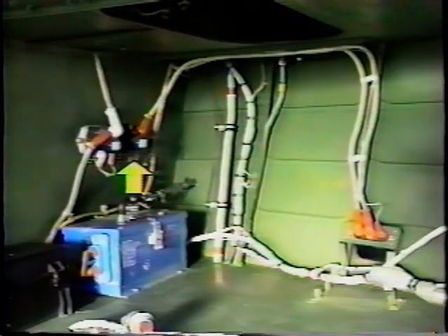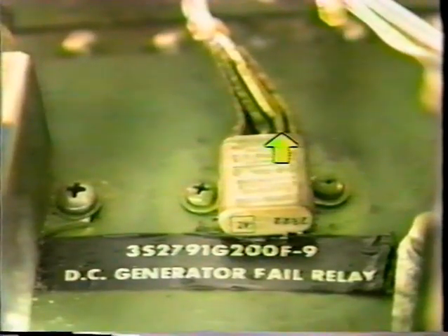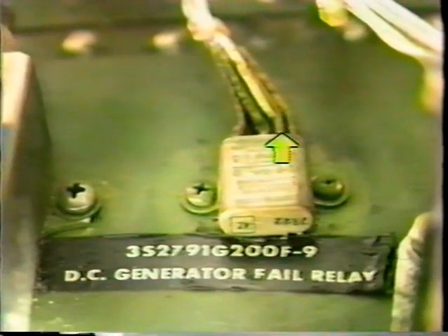Continue to follow this same wire from X1 to the generator fail relay. Follow this wire through the generator fail relay to the non-essential bus switch. With the switch in the normal position, continue the wire trace to X1 on the non-essential bus relay. This puts controlling power at the non-essential bus relay. At this point, the relay will close, so long as a good ground exists at X2 on the non-essential bus relay.